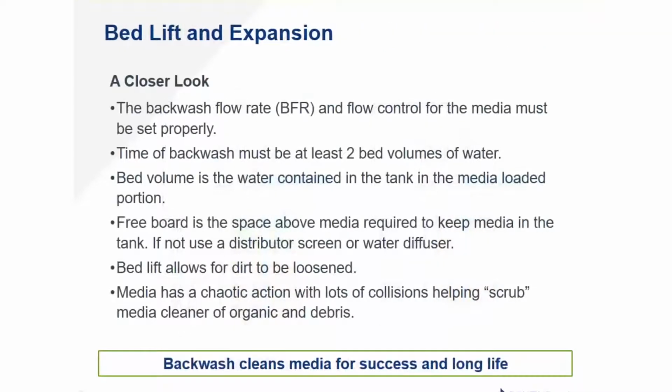So the backwash flow rate, BFR, and flow control for the media must be set properly to get the proper bed expansion. We'll look at the medias here in a minute. The time of backwash must equal at least 2 bed volumes of water for that tank.